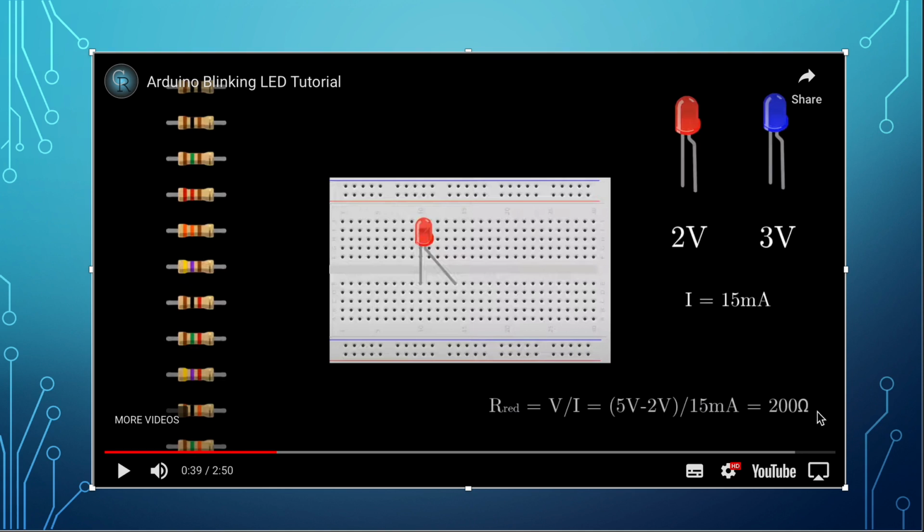So here we have 200 ohms. Let's say we used a 250 ohm resistor. The brightness of the LED bulb will be affected because we have 50 ohms more. But it is better than having a 100 ohm resistor, because the voltage will be too much and the LED would burn. So less LED light is better with respect to burning your circuit.